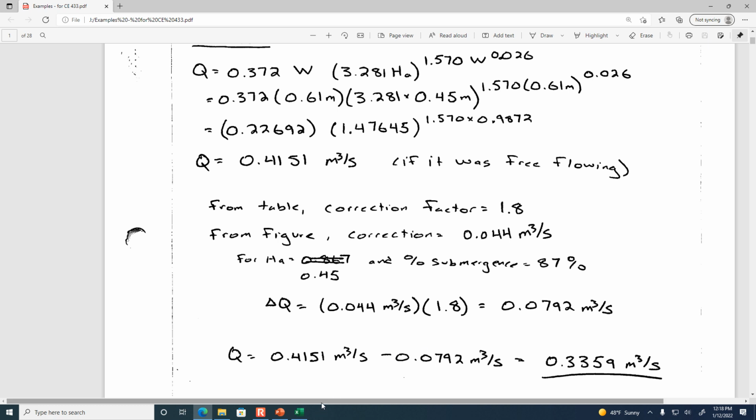But it's giving us, in most cases, enough precision to do the rest of the work that you'd need. Like if you were a farmer trying to irrigate a field and you wanted to know how much water had gotten out onto the field, you'd make a measurement with this flume, multiply it by how long you irrigated, and then that would give you the volume of water that had gotten out. Any questions about the specific calculations on this illustration?